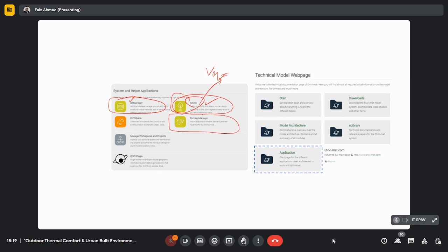Then we have something called the force manager, where we assign, for example, the ways in which simulations can be done. There are three ways. I think you have taken measurements today, right? Let us assume you have taken measurements for 1 hour. You have recorded temperature, humidity, air velocity, and radiation continuously for 1 hour, and you have the Excel data with you. Can I use that for simulation? The answer is yes, we can use that for simulation. We have to know where to give that as input.